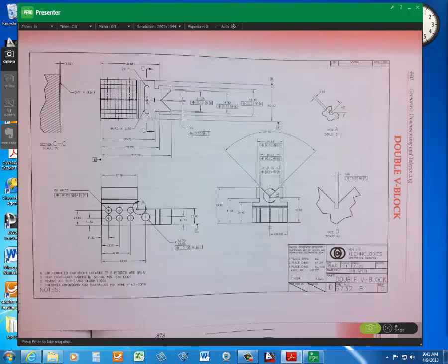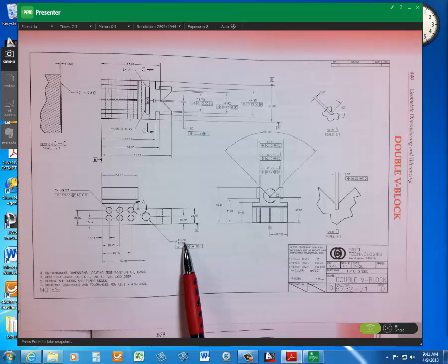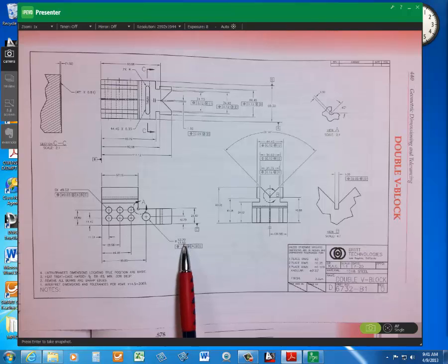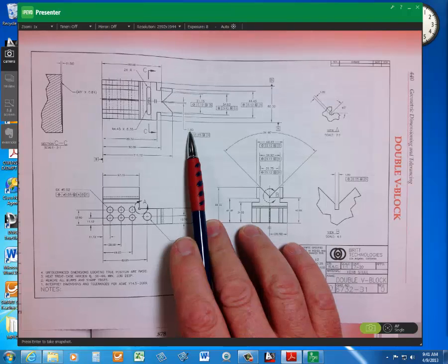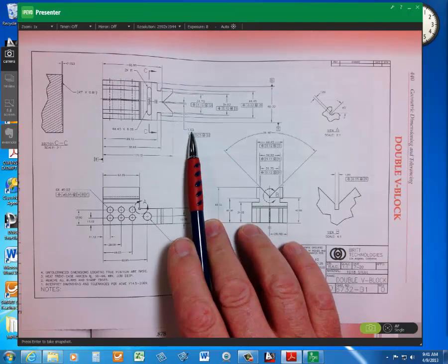No trailing zeros. No placeholders. Okay. Let's look around on here. There's one there. But now this is a tolerance. I think that's allowed for that. But a dimension by itself, no. If it's true metric, it would be 1.6.